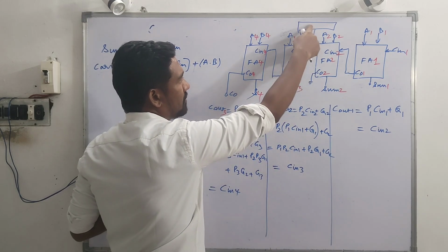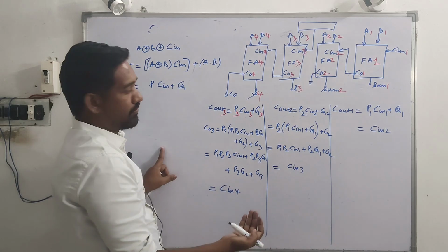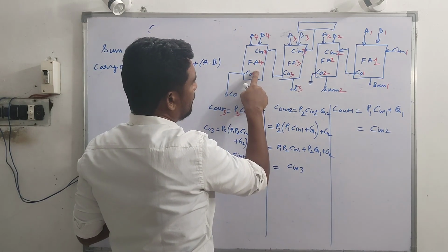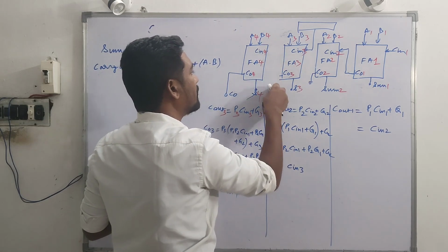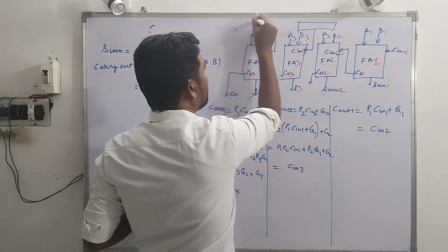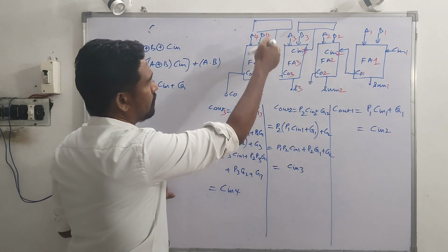We're going to have another combinational circuit, at the same time C in 1 is given, which produces C in 3. In the same way, unlike in the parallel adder, C in 4 doesn't need to wait for the commencement of C out 3. If we have another combinational circuit over here producing this one, C in 4 can be activated.